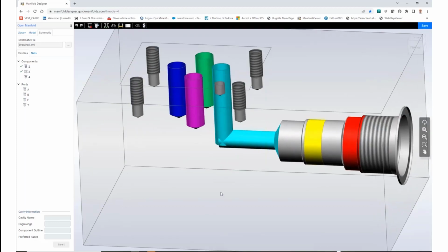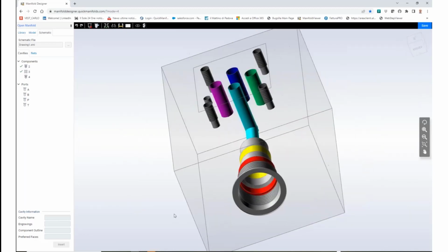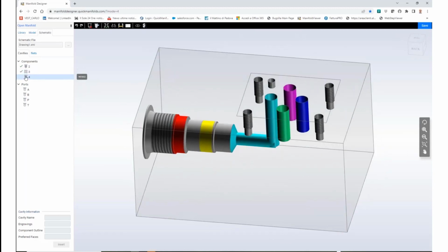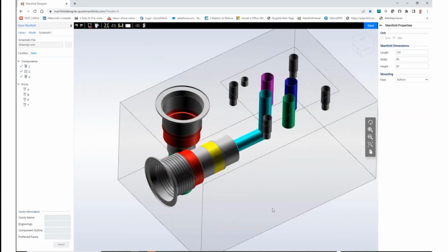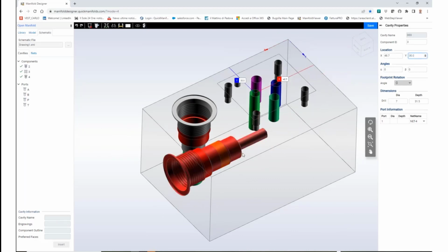And we can program this software to really behave like we want, because we don't rely in this case on any specific CAD engine. We can just drag and drop a new cavity here. And so in this case, I want to move this cavity and make it maybe 30 millimeter. And the same here, and we make it 30 as well.